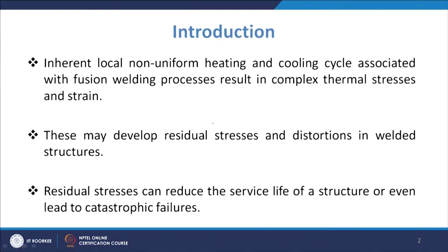So, you have the generation of thermal stresses and also strains, because when you have heating, expansion goes on, then you have cooling, then contraction goes on. That results in stress development. So, that may develop the residual stresses, and these stresses also typically result in distortions in the welded structures.